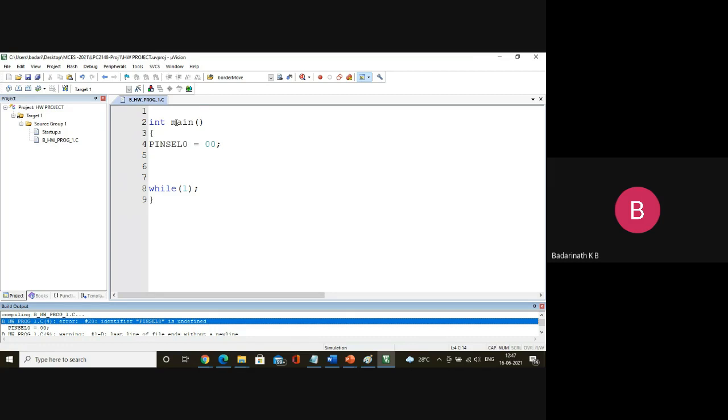So the first difference between the normal C program and embedded C program is you should make sure that you are writing this C program for a particular hardware chip, the particular microcontroller. Since you are using a particular microcontroller, a lot of registers present inside the microcontroller, I'll be using them to configure the chip before I start working with it. To implement the different logics, I'll be programming the different blocks of the microcontroller, starting from ADC to the UART, GPIO, I'll be modifying them.